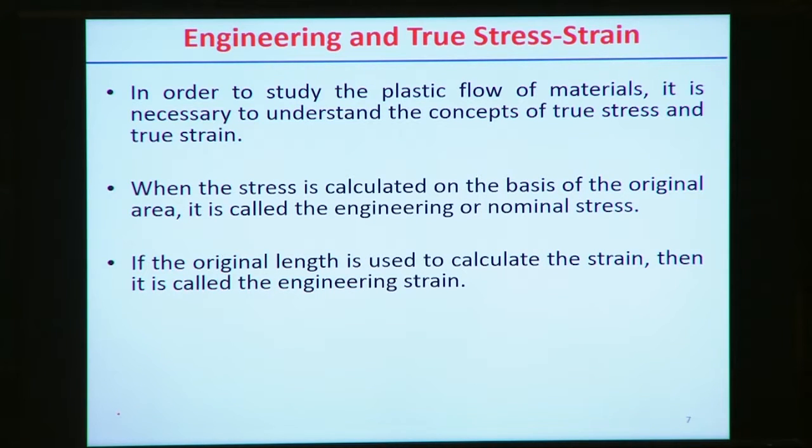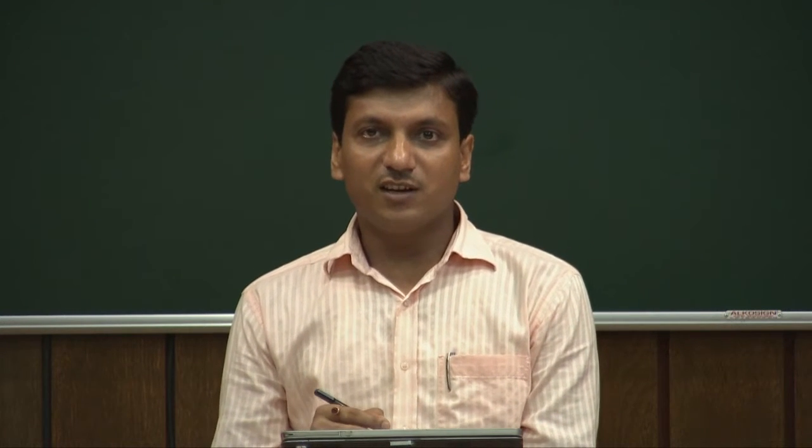Let us look into how engineering stress-strain and true stress-strain are related to each other. It is necessary to mention that engineering stress-strain is mostly used to analyze material properties up to the elastic limit. But when we cross the elastic limit into the plastic zone, true stress-strain is more appropriate to analyze the different material properties and characteristic phenomena of the stress-strain diagram with the application of mechanical load to the material.